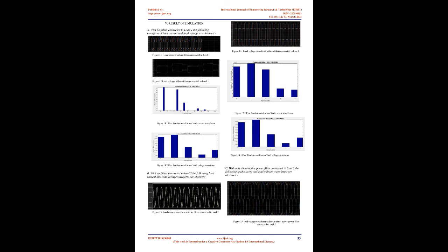The detailed model contains the following components. 1. PV array delivering a maximum of 100 kW at 1000 W/m2 sun irradiance. 2. 5 kHz DC-DC boost converter increasing voltage from PV natural voltage, 273 VDC at maximum power, to 500 VDC. Switching duty cycle is optimized by an MPPT controller that uses the incremental conductance and integral regulator technique. This MPPT system automatically varies the duty cycle in order to generate the required voltage to extract maximum power.